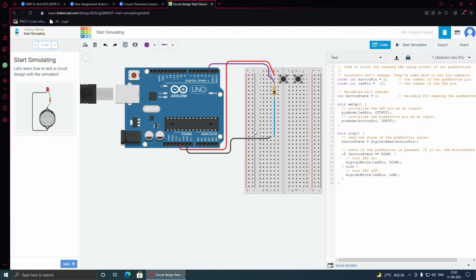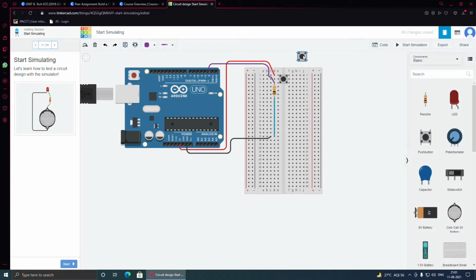So in order to connect these two push buttons in series, I'm removing the push button to show you how I placed it. We took the push button and placed it over here. Terminal 1A is placed in G1, and terminal 2A is placed in G3. Also, terminal 1B of this push button, PB2, is placed here. I've named this push button PB2 and this push button PB1.